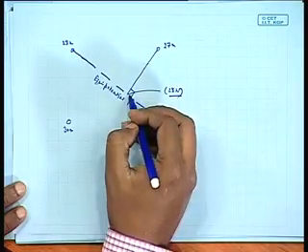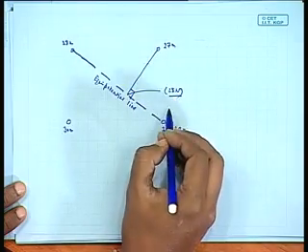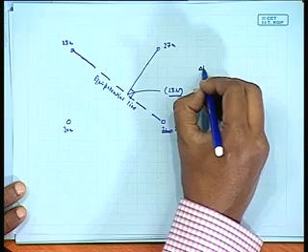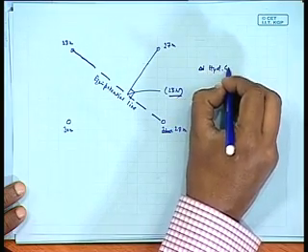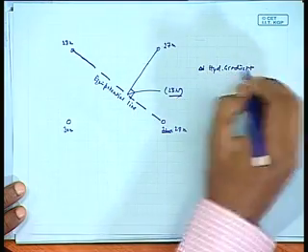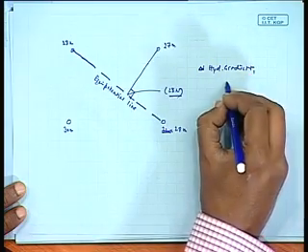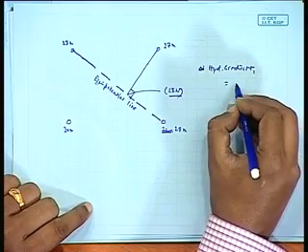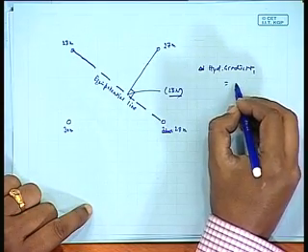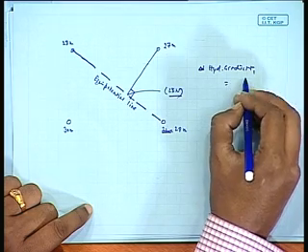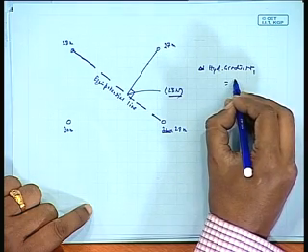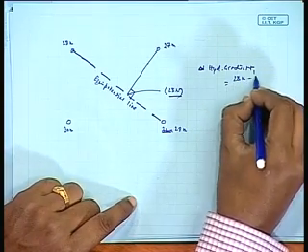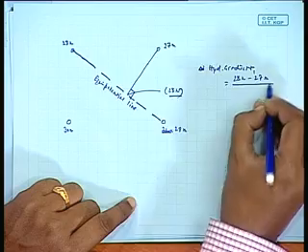From this equipotential line we would find out what is the head, the hydraulic gradient, one value of hydraulic gradient. Let us keep that as hydraulic gradient 1. We can find out the value like, say, 28 minus 27 meter divided by this distance.